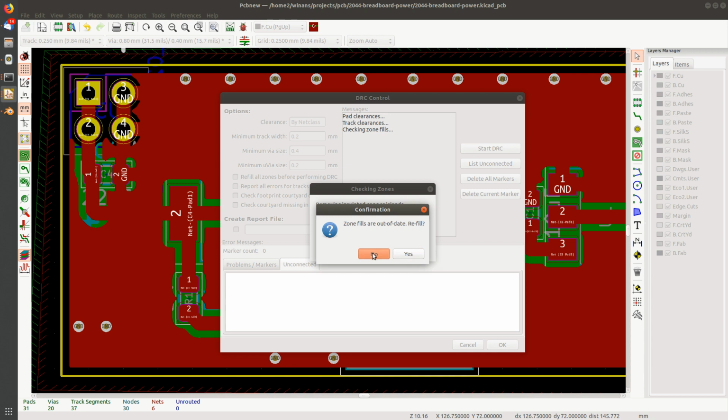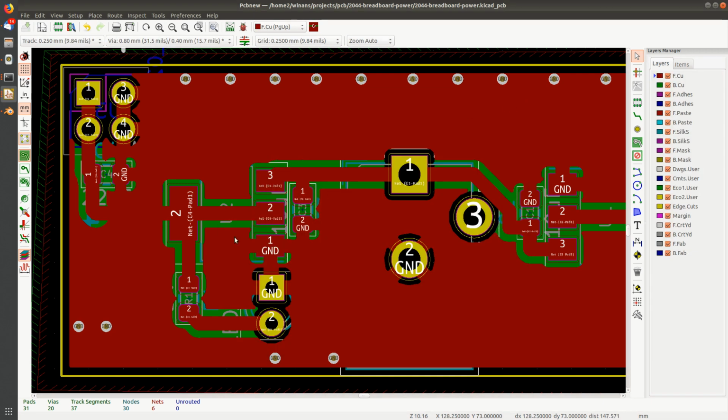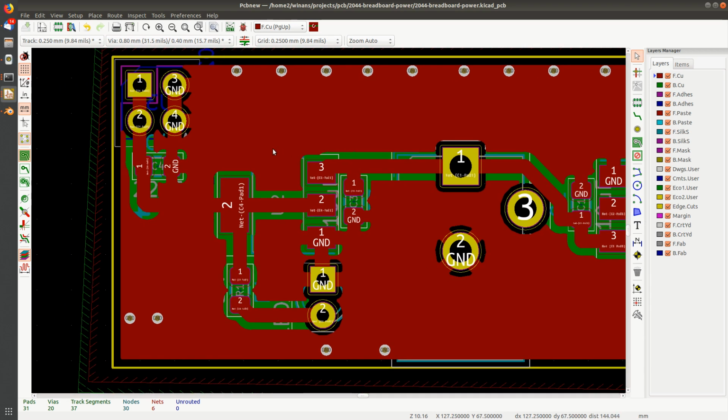It should have done that. KiCad, you're screwing me up here. Because it should have said I'm shorting my power and my ground together right now. Okay, whatever. I did all that on purpose anyway, just to see what it would do. That's not very nice. But it did fail to report an error after I told it to ignore the other error, which was you need to redo your ground, your filled regions.